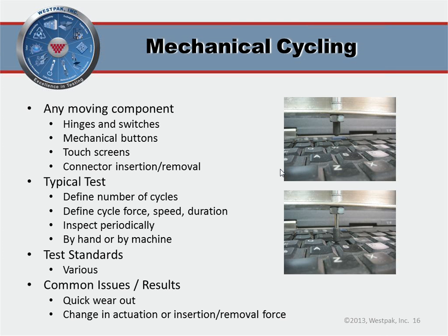So cycling is basically life cycle testing any moving component. On our laptop, the big hinge on the display is one thing, different buttons, the keyboard and all the other little buttons and switches, the touch screen or the trackpad, and then all the connectors, all the ports, the USB port, everything. Those will be used many, many times throughout the product's life cycle. Will they last a million cycles?